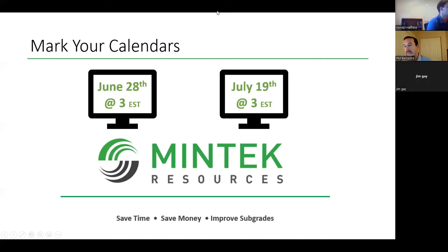My only thought was, was there a treated proctor versus just an untreated proctor done? Because we know that to be true in the field a lot of times, that there's not, and you have a geotech out there who's testing your moisture contents, and he's coming up with a number that's still over, but is it really?